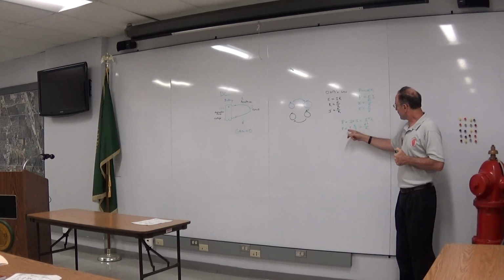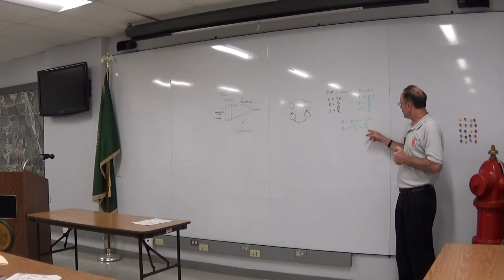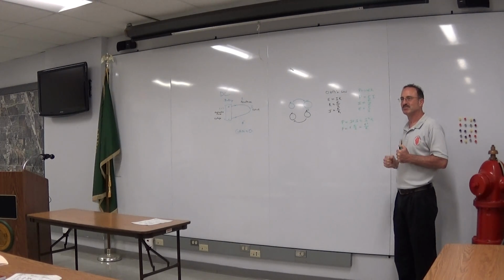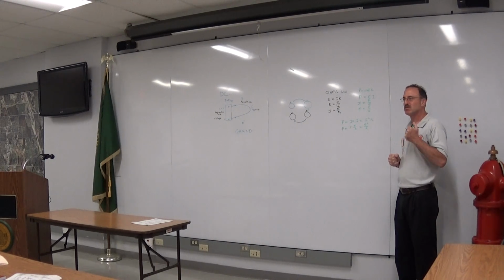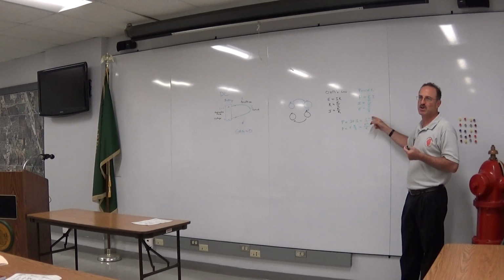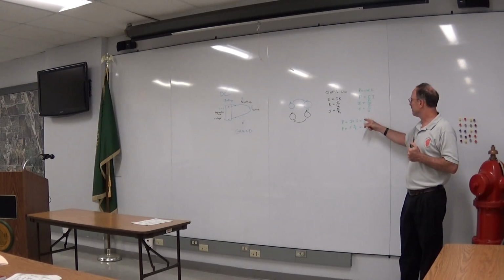So if the resistance is fixed and the power you want to minimize, what do you do? Well, let's go over to I squared R. These are called I squared R losses, in fact.